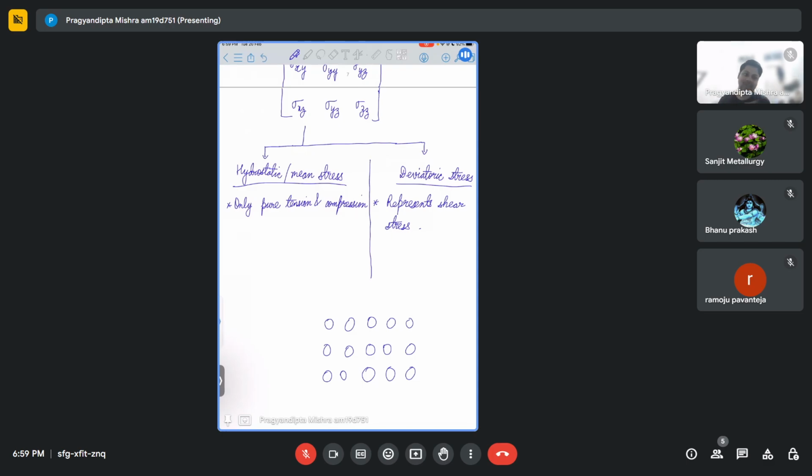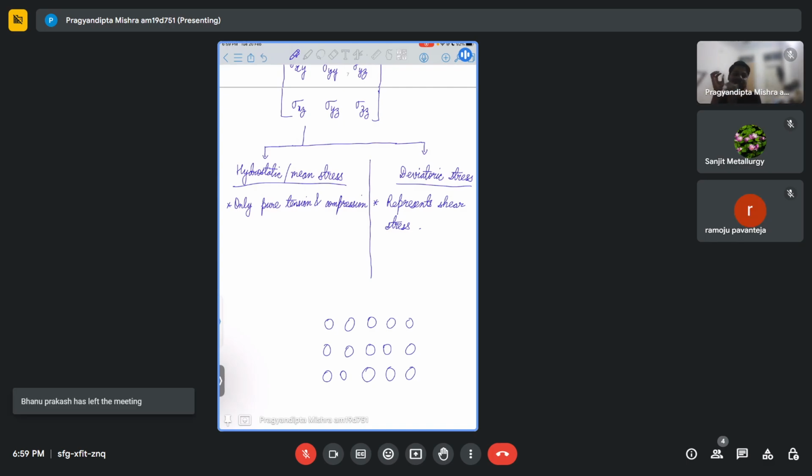I'll not tell you exactly what dislocation is, but because of this dislocation, your atoms are not ordered correctly. If there is some gap, an atom will jump from one position to the next position instead of just staying in one position. Because of this jump, your material does not fail. Understand that. The material does not fail, but it starts flowing, or it starts yielding.